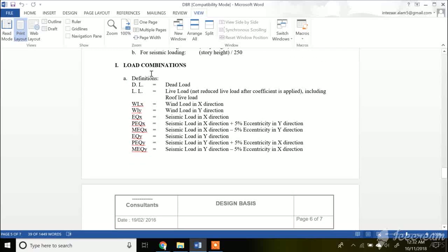We have already done the loadings. Now the important part which we have not covered is the load combination. The load combination is your dead load, then your live load, then wind coming around. Wind can come along both directions, like x, y and z if your software has that axes system. For the plan area, in the long and transverse directions, wind will blow in both directions, negative as well as positive.